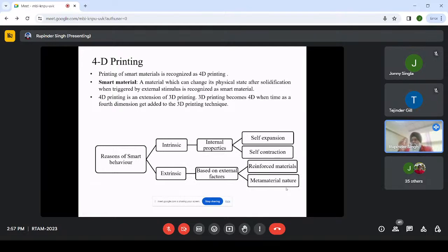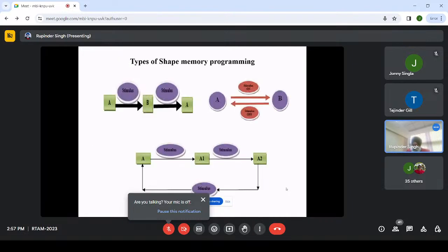So these metamaterial structures are really important when I am going for implant design, because I want to keep the 3D printed component as light as possible, with a high strength-to-weight ratio, and I want the osteoblast cells to grow in a good way. For these types of capabilities, the metamaterial has a lot of meaning, specifically in 4D, because I will be able to manage the modulus of toughness and Young's modulus in a much better way as compared to the solid section, right?